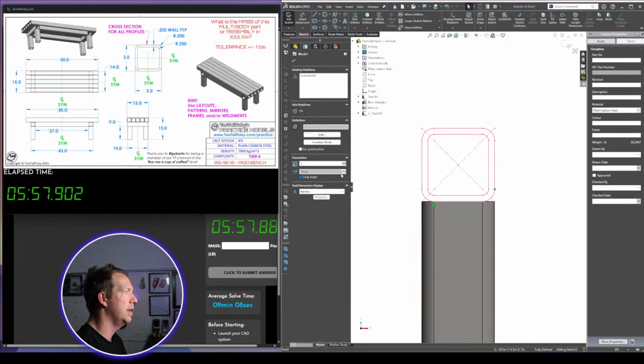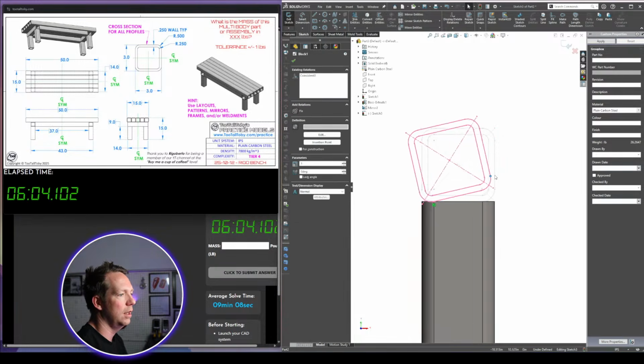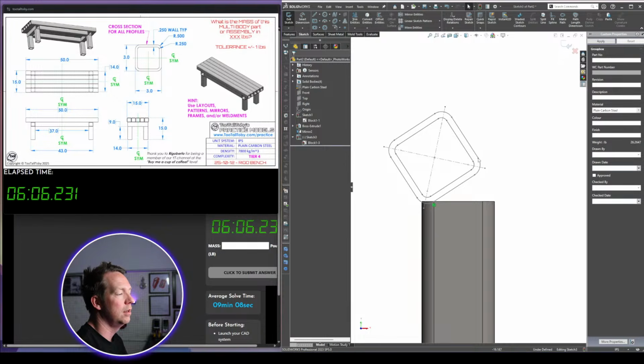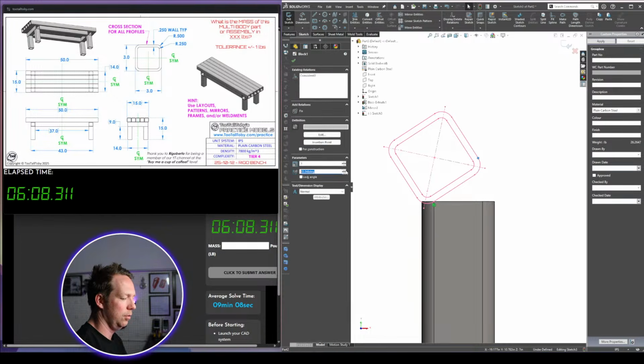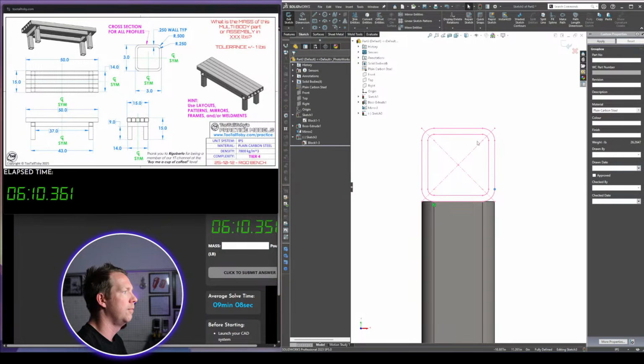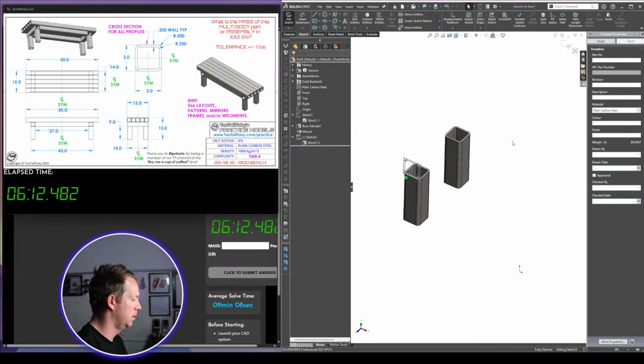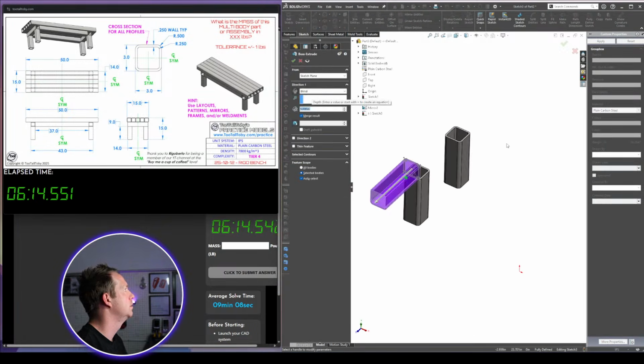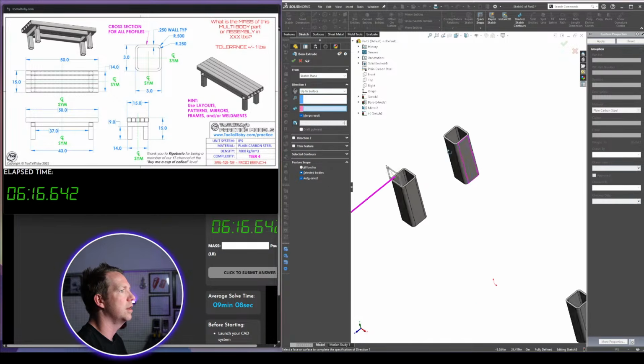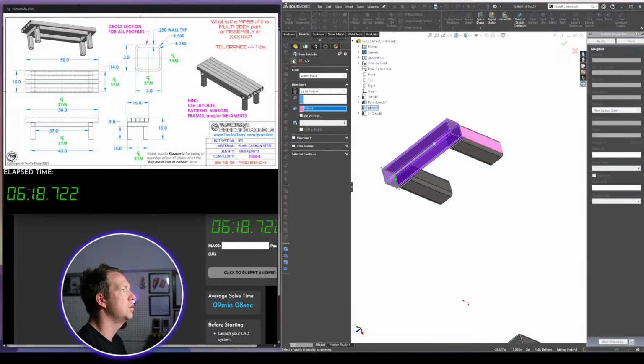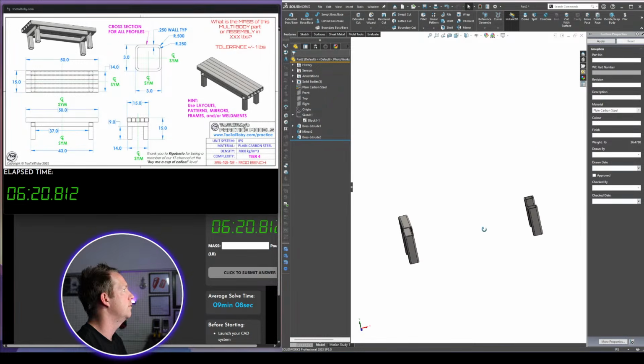If I grab that and uncheck lock angle, then it wouldn't be fully defined, because then I could go like this and it's underdefined. If I grab the block, put that angle back to 0, press lock, it's once again fully defined. And then I can extrude it, and in this case I can go up to surface, uncheck merge, and leave it like that.